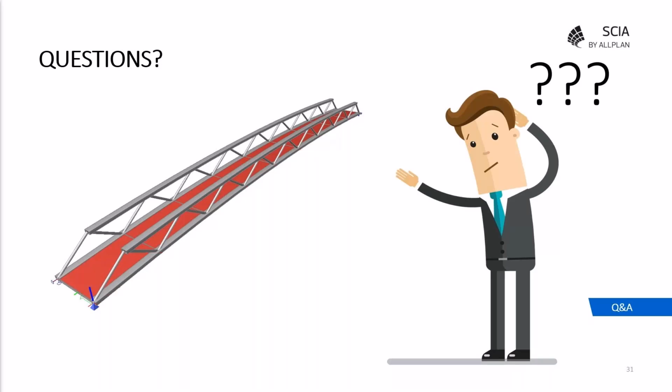For other types of structures, because of course the harmonic analysis is not really only for footbridges, it can be used for machines acting on certain floors, etc. In that case, it can be that the damping will not be constant along the ranges of frequencies, and in that case, you can use the Rayleigh damping.